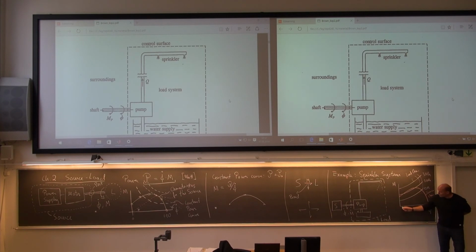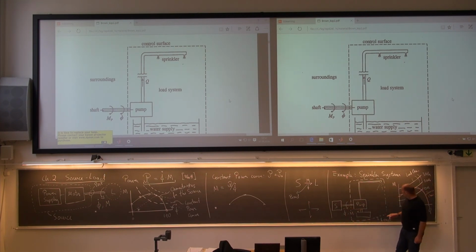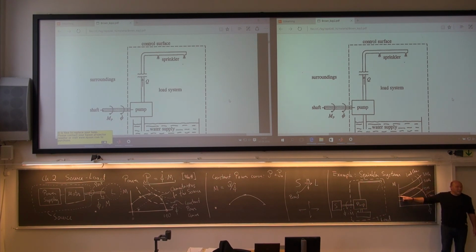You switch on the source, and we start everything at rest, no rotational speed. This is the requirement from the load to get things even to start to move. This is what the source can provide us with in torque. Yes, it is bigger than the load. This looks promising. It will start to move. So yes, we will increase the rotational speed. And here the torque is bigger than the load.